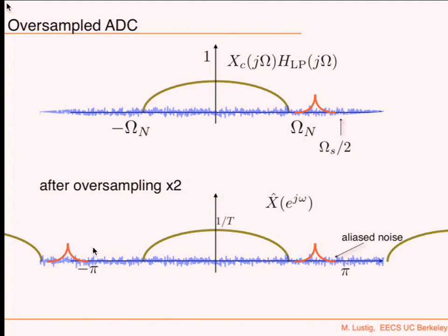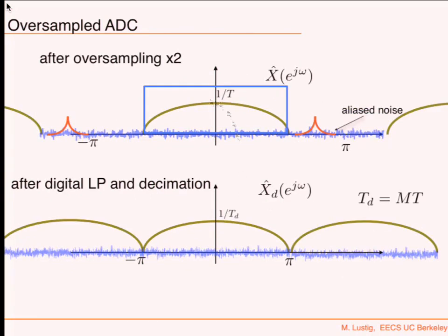Now what I could do, if I just want this part of the spectrum, what do I need to do now? Low-pass filter, but now we're in the digital domain, right? These are just samples represented on a computer, right? I can just type it down, right? Run it through a low-pass filter, and I'm representing here an ideal one, but of course, again, it's not going to be ideal. But I can make it sharper, or to some specs, much more easily than I could with a bunch of capacitors and inductors, or maybe an op-amp, because those might change with temperature, right?